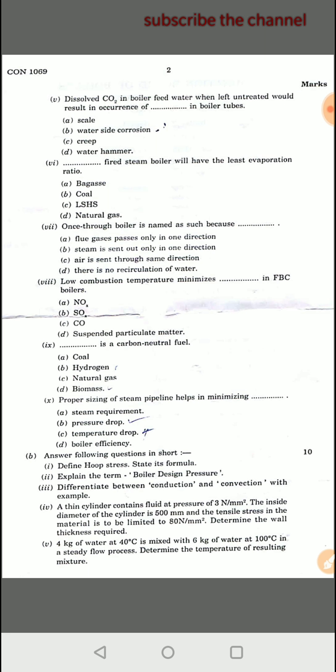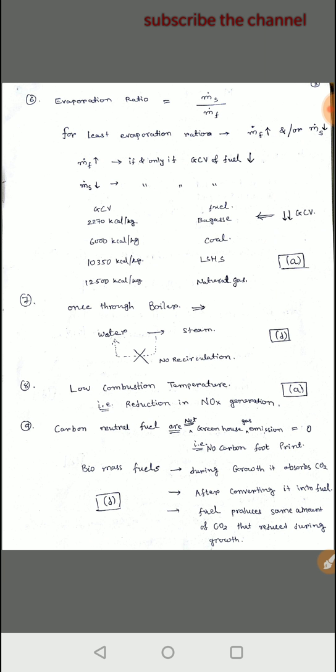Question 6. Blank fired steam boiler will have the least evaporation ratio. To answer this question, first of all we have to find out what evaporation ratio is. Evaporation ratio is the mass flow rate of steam divided by the mass flow rate of fuel supplied to generate that quantity of steam.